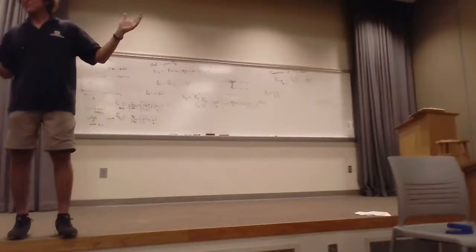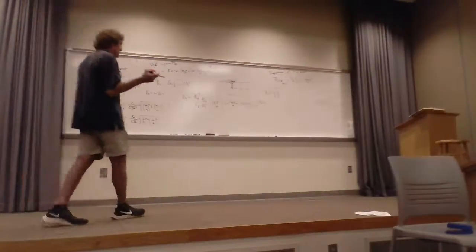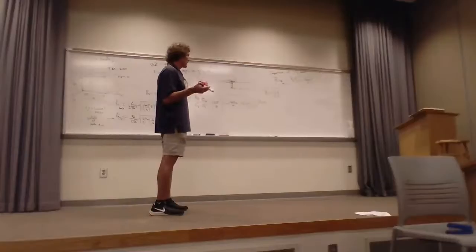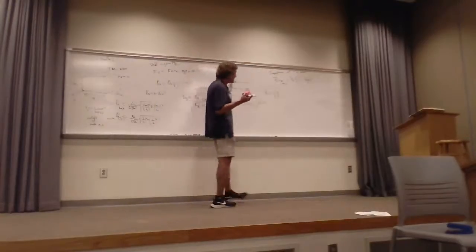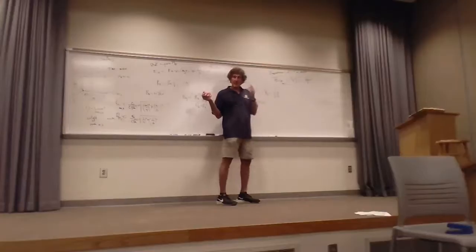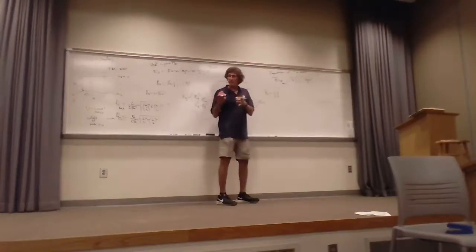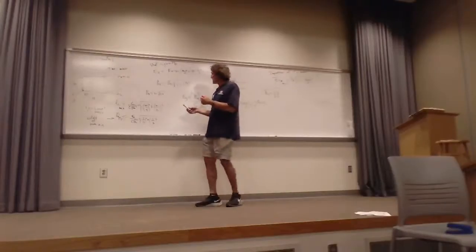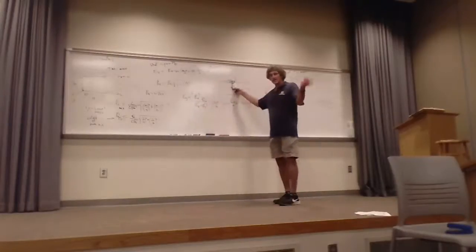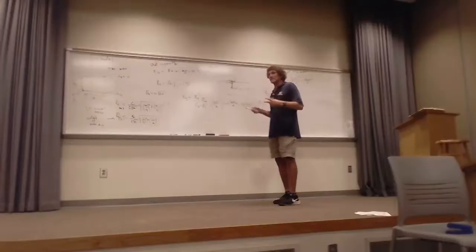I mean, you would not have a lossy guide for any meaningful work. So that is the intrinsic impedance. And the idea is this. If you're going to feed a waveguide, you have to make sure that the impedance of that coax cable feeding that is the same as the impedance of the guide for the mode you're feeding.